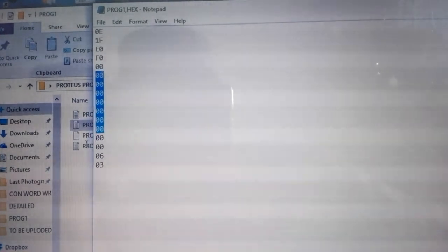On the fourth location we have F, which is the code for halt, and then we have 0, it might be 0 1 2 3 up to F. This is a don't care nibble, the lower nibble with the halt and out instruction, it is don't care. And then I have filled all the rest of the addresses with 0. So this is how I have written this program.